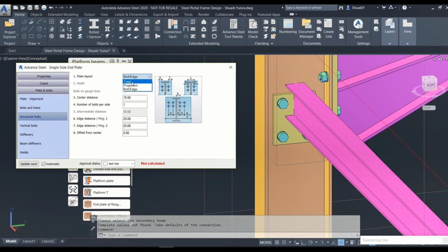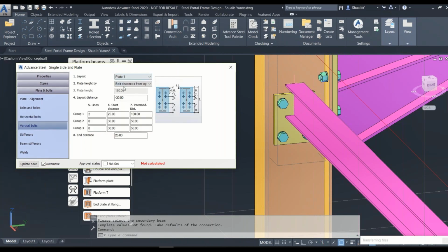So these are the different type of positionings. If you set it to total, that block below it for the width becomes available to edit. So use total. If you see 120, you see it updated, right? But what I normally do is I go to the vertical bolts, I go to middle, right? And then you can see it jumps to a good position.